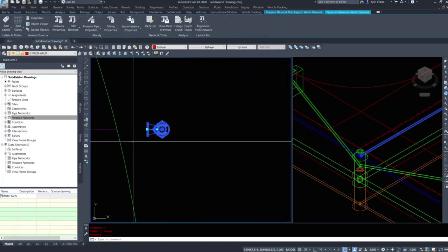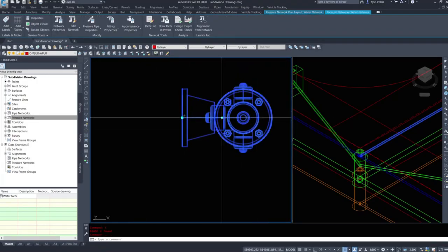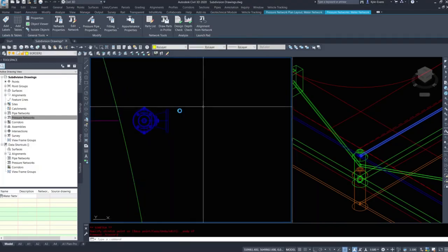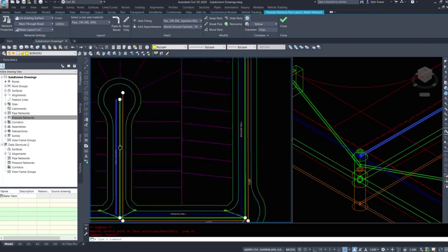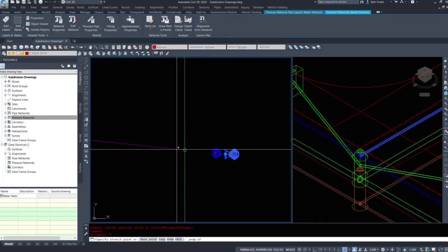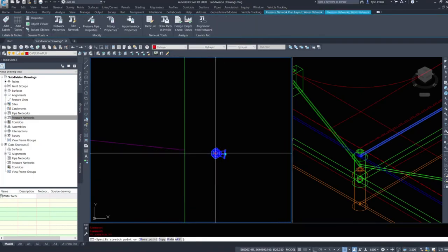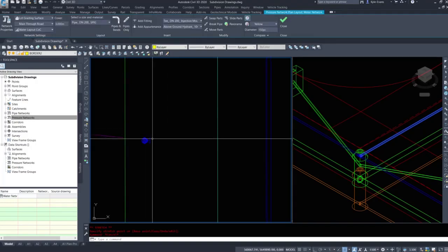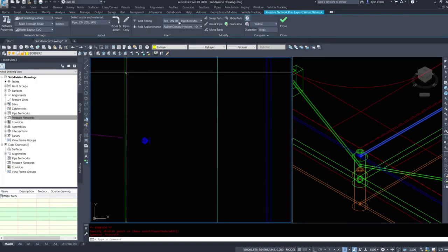And now if we look at this, it comes in pointing to the east. However, you want the pipe connection pointing towards your water line. So from here straight out. And the same with this one. And go into the settings and get the actual sizes. This is a 100 millimeter pipe coming off this fire hydrant.